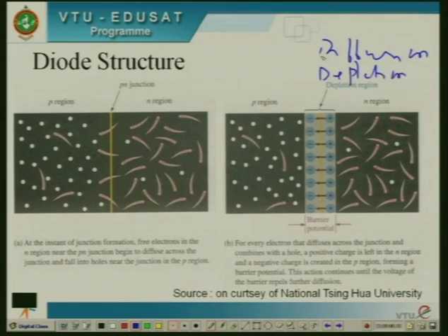During the diffusion process, the electrons form a potential barrier. When that potential barrier exists, a few more charge carriers, strongly negative electrons and strongly positive holes, try to diffuse through the channel, but the net current is 0, because at the same time, due to the minority charge carriers, charge carriers drift from one region to the other. The net current is 0, and at the equilibrium state there is no current flowing through the PN junction when it is open circuited.